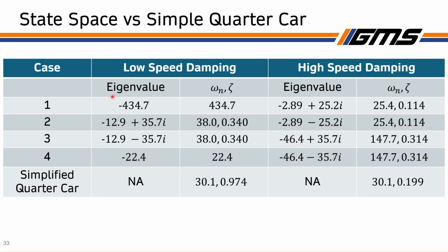So in general, when you are looking at your eigenvalues, your goal here is to choose a setup where you have very few eigenvalues with imaginary components. And you want the imaginary components of those eigenvalues to be as small as possible, right? So you can see over here, this is not a super great setup because the eigenvalues are mostly imaginary, especially for these ones. This one is a little bit less imaginary, but all of these have imaginary components. So you're going to have two frequencies happening at the same time. And obviously that's not very ideal, right?